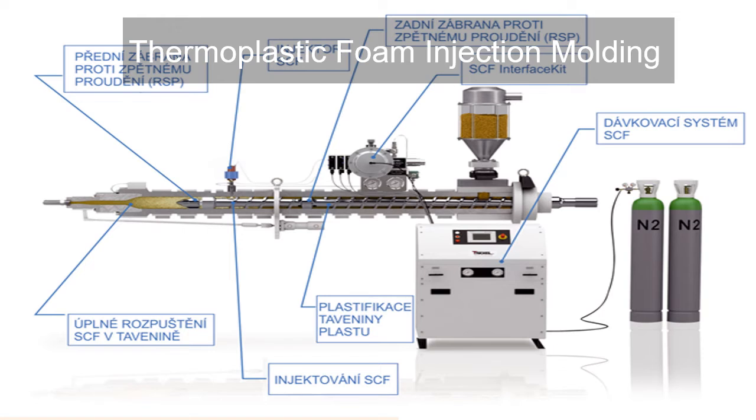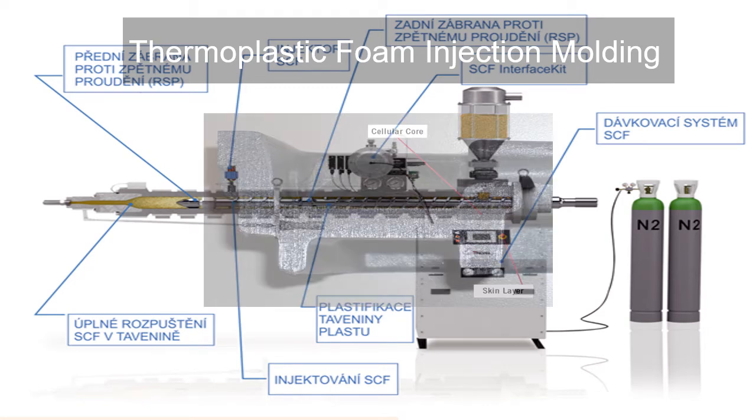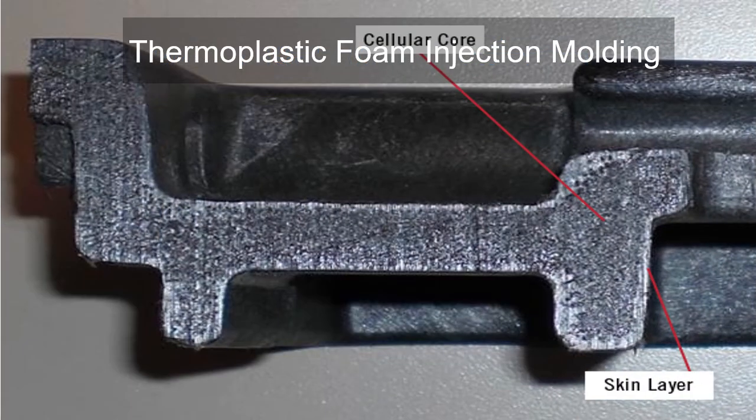This can be produced either by introducing gas into the molten plastic in the injection unit, or by mixing gas-producing ingredients with the starting pellets. A small amount of the melt is injected into a mold cavity, where it expands to fill the cavity. The foam contacting the cold mold surface collapses to form the dense skin, while the core retains a cellular structure.